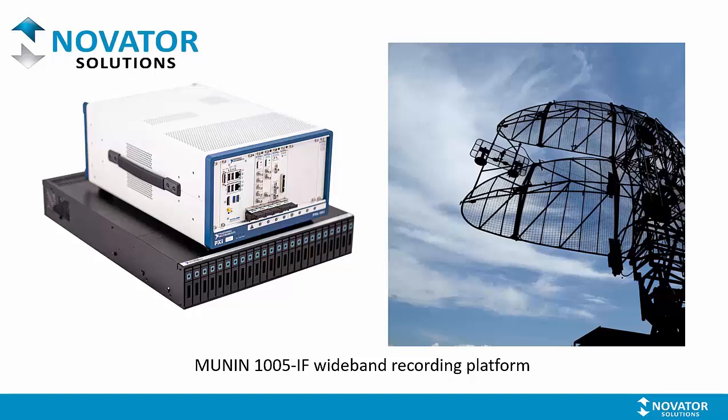Munin 1005 is an IF recording platform that ensures gapless recordings on narrowband and wideband signals ranging from 2 MHz to 600 MHz real-time bandwidth. This configurable platform is ideal for capturing one or more IF channels in real time, for device under test characterization and spectrum analysis. Munin uses a modular PXIe platform, ultrascale FPGAs, and RAID disk storage.